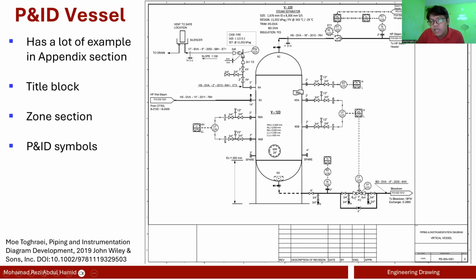And then another one here is this control valve. Basically, these are connected to this line. So these are the same. These are 2 inch flange or pipe nozzle connected to this 3/4 inch gate valve. Another relief line, I guess, a gas relief line. I think 3/4, and then your capillary tubing.